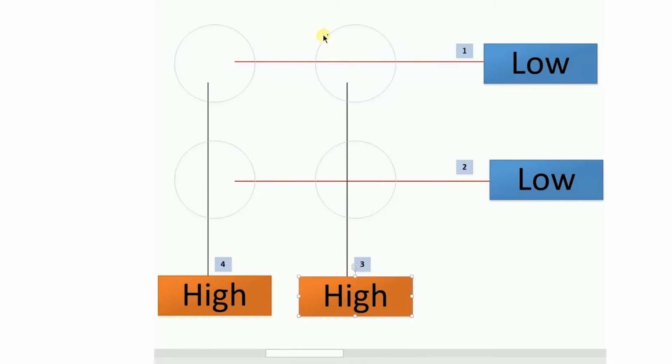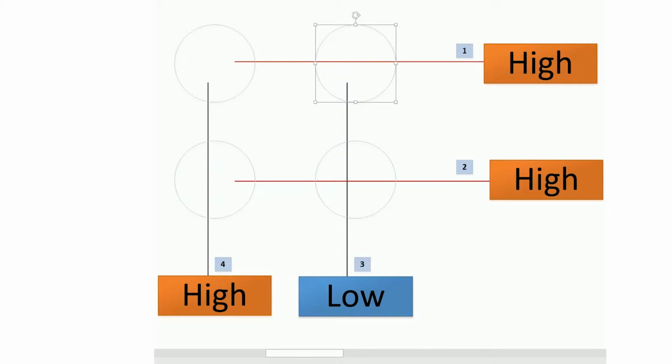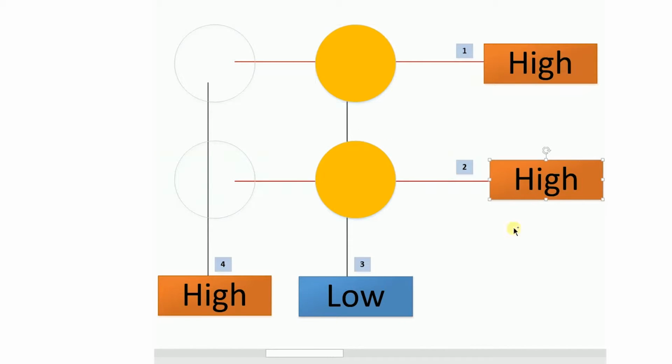First of all, we're going to set the column to low. So basically turning the column on. And since we want this LED on, we're going to turn pin 2 on high. And since we want this LED on, we're going to turn pin 1 on high. So these LEDs would turn on. Alright, so we blink it really fast and then we turn it off.